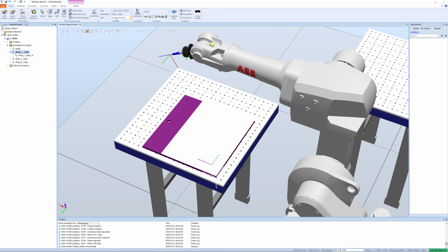Define that. Tool is correct, that's fine. And in the bottom, when we define motions, target robot targets, we can define how we do this. So we try with MoveL as default. Alternatively, it could be MoveJ and so forth, but that could be fine. If we need to change that, we do that later on.